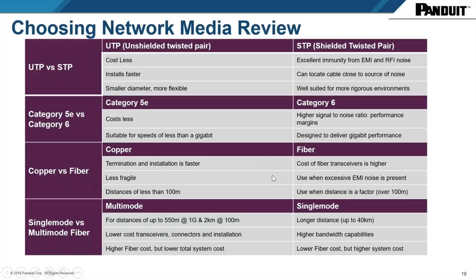The EMI protection is higher for fiber. Why? Because fiber is not affected by power systems. So light and power, that's not a concern there. When you look at the fiber, having single mode versus multi-mode also is determined by how far you can run these cables. Multi-mode fiber, for instance, could take you up to 2 kilometers. When you go single mode, and that's a very expensive type of cable, you could go to 40 kilometers.